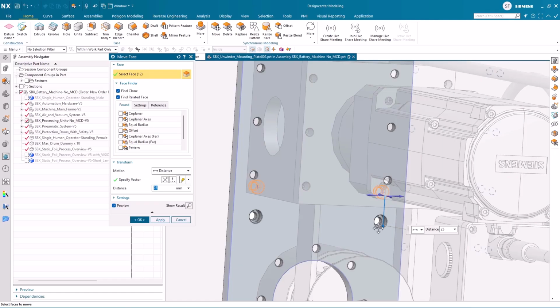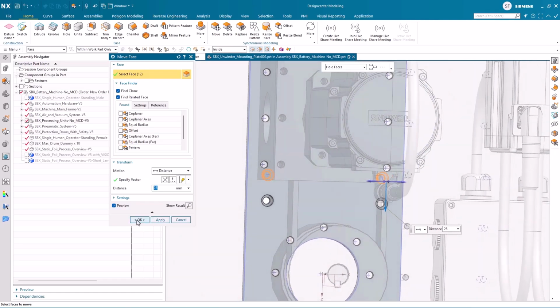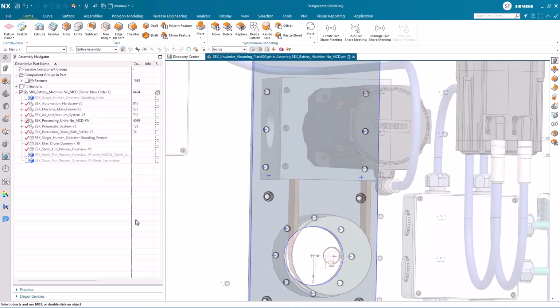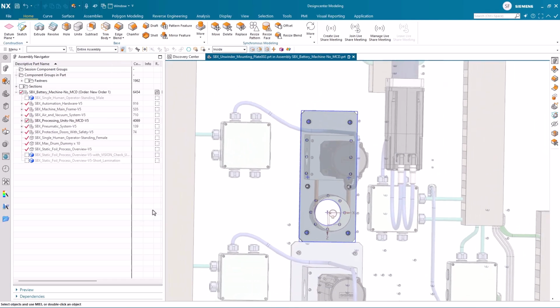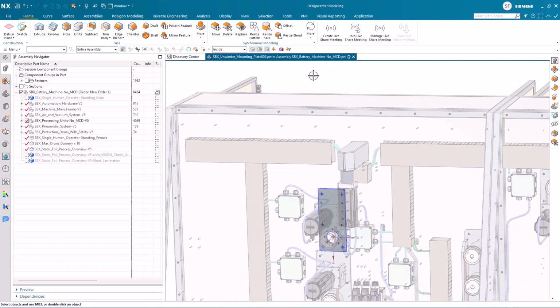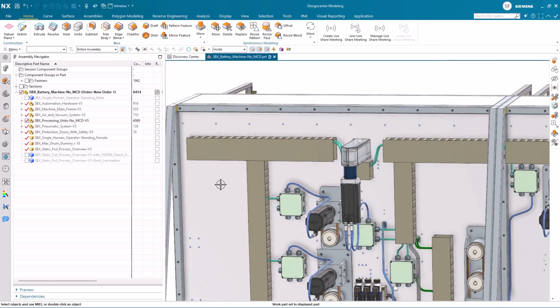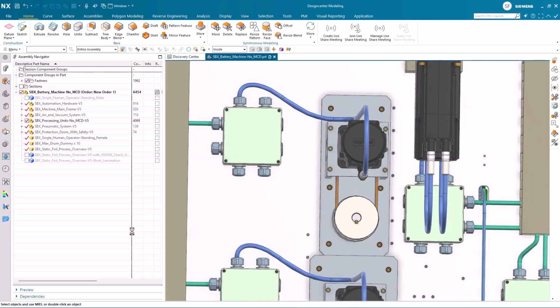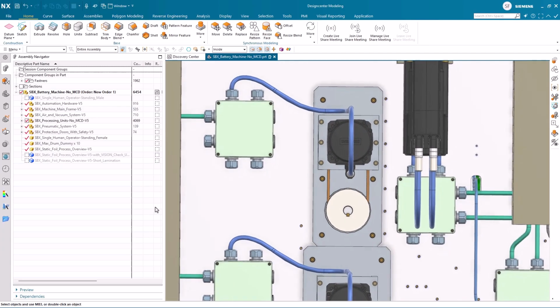So when I do that now, I'll make sure everything else is still properly aligned, that all the holes in the other plates moved, all the screws, all the fasteners come back to where they need to be. So now that I have my design done, I'm going to go ahead and do that. So remember, I said to work on the displayed part on the assembly again. I'm going to turn back on my fasteners, and I notice all my holes and fasteners line up. Great. Our first task for the day is done, and we got some help.